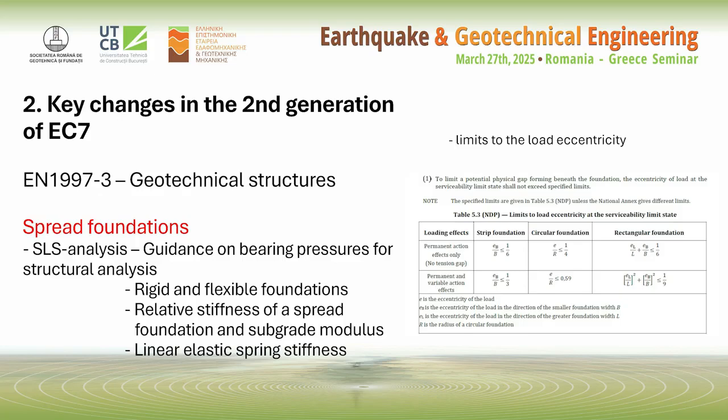Also, and I know that there are many structural engineers here in the room, you will find very useful guidance for SLS analysis on bearing pressures for structural analysis, for rigid and flexible foundations, how to determine the relative stiffness of a spread foundation and how to determine the subgrade modulus, and also how to use the linear elastic spring stiffness. And there are also recommended values, again an NDP, for the limits for the load eccentricity. And these are, I think, useful data for both geotechnical and structural engineers.